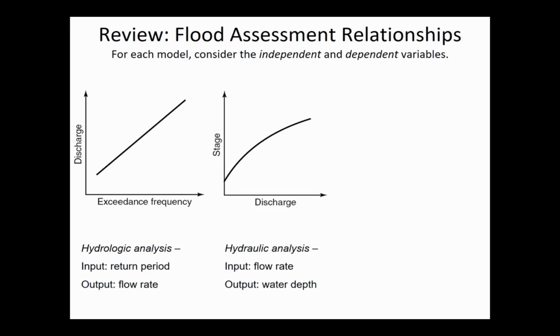And so essentially, you know for the 2-year storm, how deep the water will be, because the hydrologic model told you the discharge, and the hydraulic model told you the depth. So we essentially know how deep the water will be, and how often. Maybe once every 10 years, the water depth will be 10 feet. Once every 50 years, the water depth will be 12 feet.